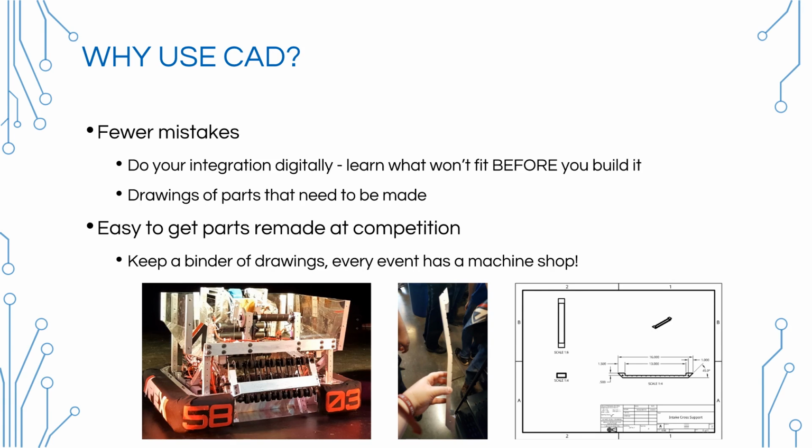Yeah, and we actually experienced that last season. On Apex, you can see the intake crossbar right above between the sets of wheels and the front gap that sucked up fuel. Well, it's there to protect the intake from damage if we took a hard hit. It did its job. It protected the intake, but it also got really busted, as you can see in the second picture. And this was I think the second time that it happened.